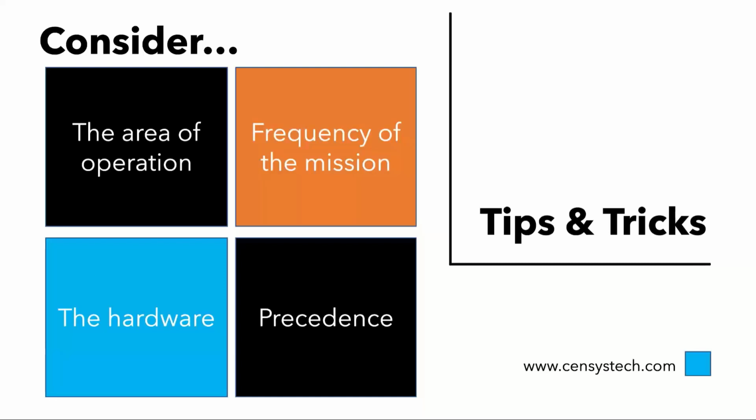So starting the roadmap, well, where's the area of operation? It always makes sense to start with a geographically constrained BVLOS waiver. That makes a lot of sense because you're able to start building that operational history with a low risk of getting denied if the area fits the bill. If you're asking to fly BVLOS over Manhattan, you have a lower chance of success than flying BVLOS in a sparsely populated area in Class G airspace. One of them is way easier than the other.